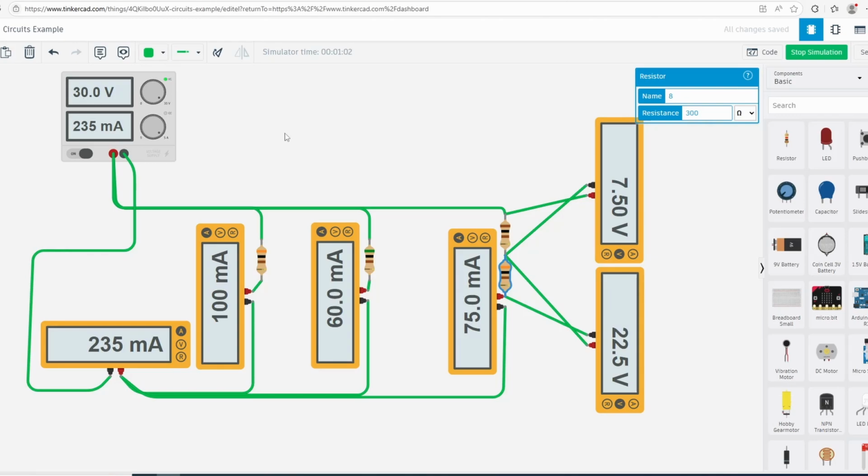What you just saw there is Kirchhoff's voltage and current laws. Kirchhoff's voltage law states that the voltage drops in a path loop add up to 0. Kirchhoff's current law states that the currents going into a junction need to equal the currents going out of it.